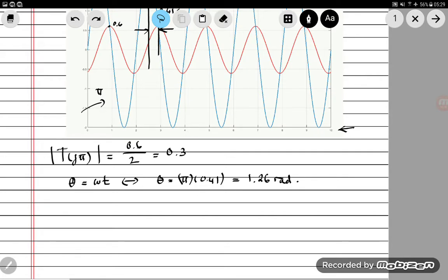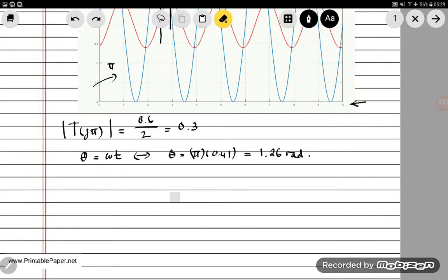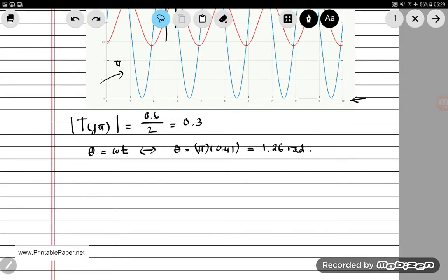And we will have to recalculate those factors or numbers for every frequency of interest. And this is exactly where the Bode plot becomes useful. Instead of calculating the magnitude of the frequency response transfer function and the angle at every frequency of interest, we determine these numbers as a function of omega or frequency.